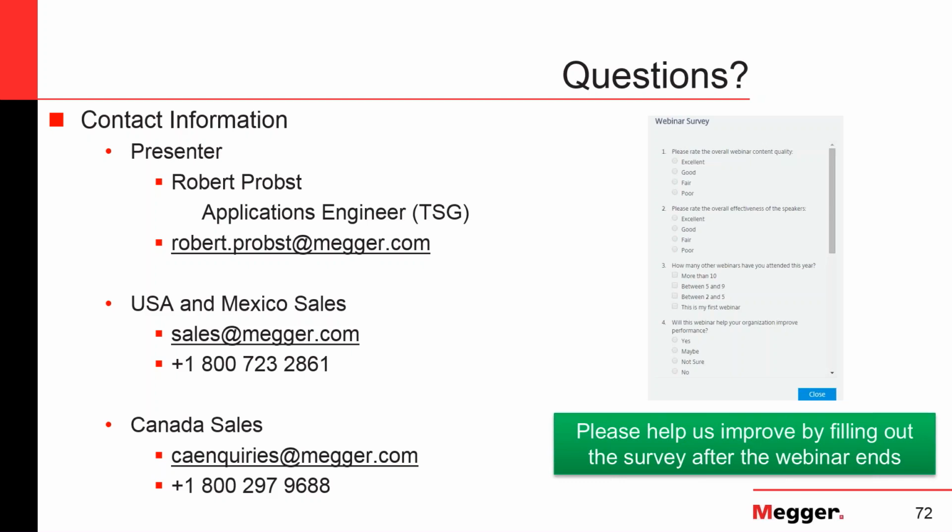So actually in the medium voltage world, primary injection is also used. It's not just for the low voltage applications. I just had to focus the presentation because of the time restrictions. But it is also a very common method in the medium voltage world to test the entire system, CT, relay, circuit breaker. You want to add to that, John?